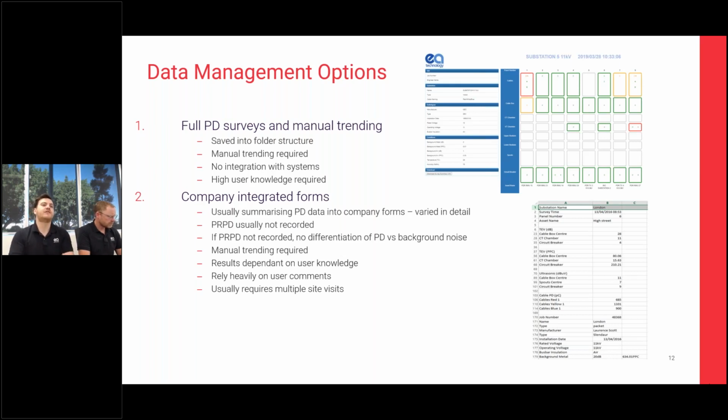Something that a lot of our clients do is they try to integrate this PD into their own company forms. And what that does require is a summarization of the PD data into more general data points. Now, a lot of our companies will summarize it into the amplitudes of the PD sources or the pulses per cycle in terms of TEV, or even the interpretations that are built into the Plus 2.